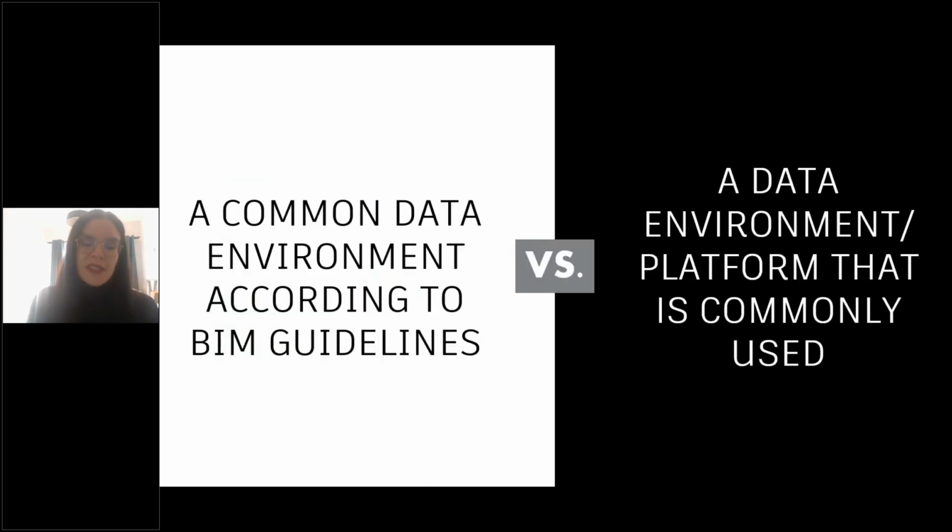Now, with that being said, I do want to point out that there is actually a difference between a common data environment, CDE, according to the BIM guidelines, and those are both General BIM guidelines and ISO 19650, versus a data environment or platform that is commonly used. To give you an idea, you could say something like a Dropbox is a data environment that is commonly used. It's not necessarily a CDE according to the BIM guidelines.